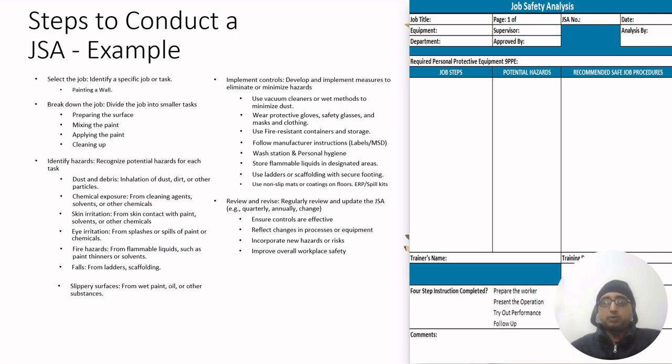First of all, make sure that the equipment you are using is not underrated, is up to the mark, and is rated for the load. Secondly, make sure that the area is barricaded and cleared of obstruction, so no collisions happen. Similarly, make sure that the speed or the swing of the equipment is under the limitations, so equipment failure can be avoided. Similarly, make sure that all the equipment we are using is already inspected and in good shape, so equipment failure can be avoided.